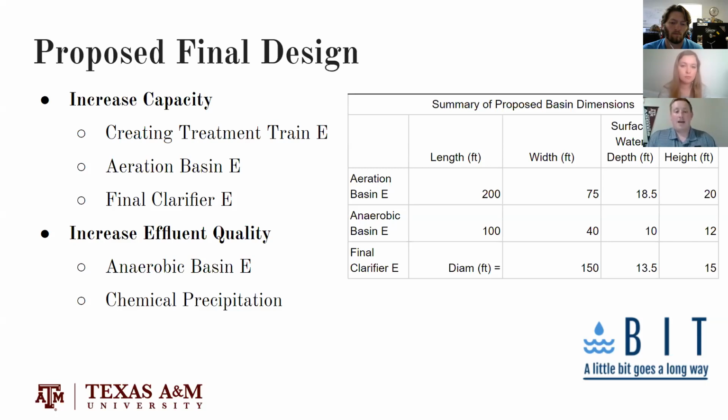So by the time that all of the raw wastewater enters the aeration basin, the phosphorus accumulating organisms have had time to build and increase their population to a point where they can digest and eat up a lot more phosphorus, and that ultimate phosphorus concentration in the effluent would be lower.